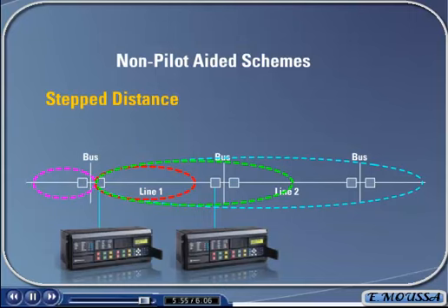These relays will then proceed to open the breaker and clear the fault from their own respective end of the line. Each relay will also have ground stepped distance zones of protection, which are identical to that of the phase stepped distance zones. The difference being that the ground distance elements are used to detect single phase to ground faults.